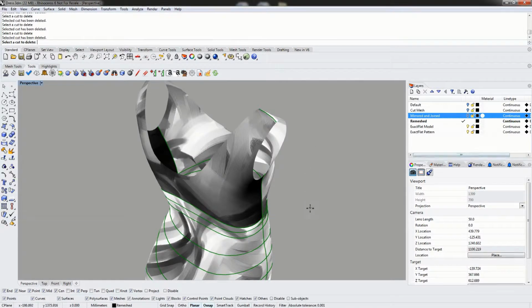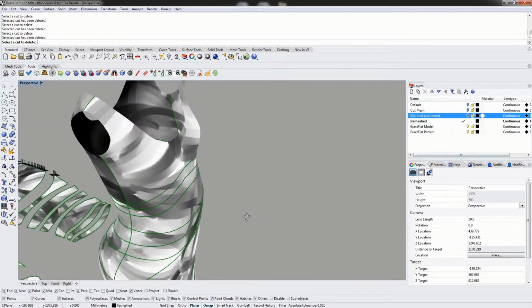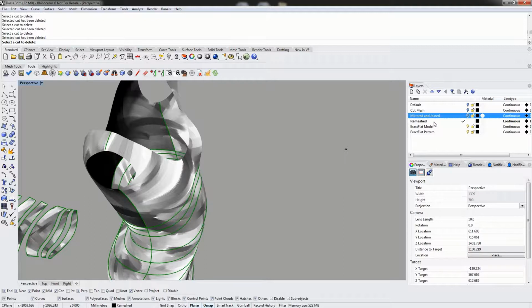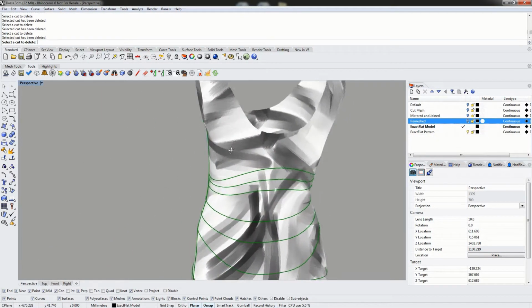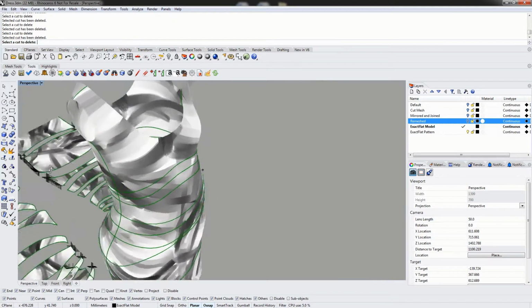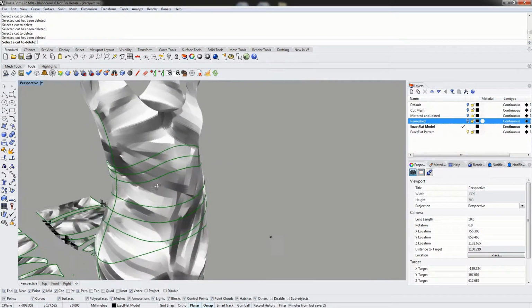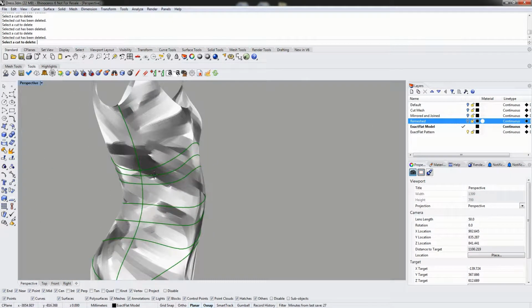We're getting this tearing or flickering effect, probably because we've got both the rendered mesh and the reference model mesh over top. So we're going to make our model layer the default layer, and we'll turn off our rendered mesh. Now we don't have two meshes occupying the same space. So we're going to continue, we're going to remove some additional cuts here. We're going to make sure as we remove a cut on the front, we're also going to remove the same cut on the back hand side.